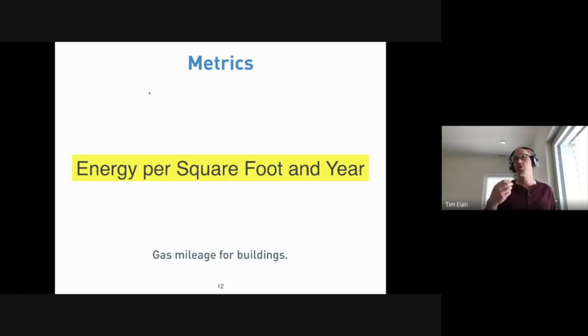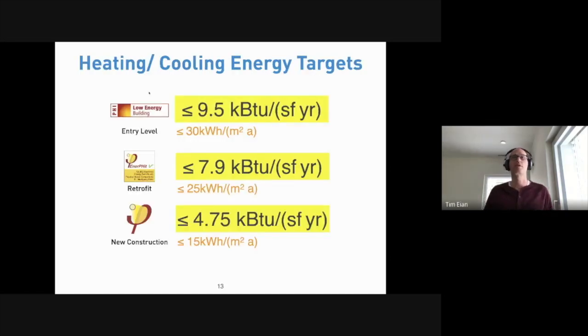But generally, for a passive house, we're looking at either what we call useful energy, that's the actual energy input into the building, or we're looking at source energy, where we track it all the way back to the plant or the origin. And these are key markers that we look at. In terms of the useful energy, the one that stands out the most here in our cold climate is the heating demand, certainly. And with that, here are some of the targets, both metric and in IP.